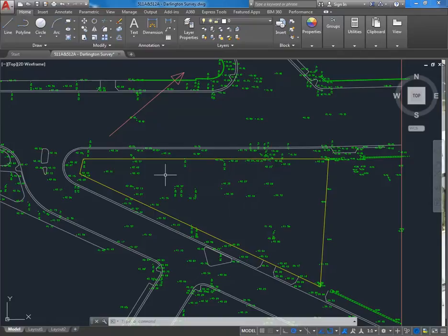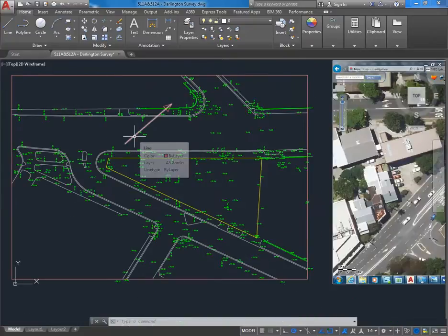And so these are the things you should be thinking about when you first set up your project. How are your plans going to be oriented, and how do you maybe need to then organise your other drawings to work with that? Don't always think you need to orient them to true north. That's a common mistake. People think that because engineers and other people often orient their drawings that way, that you need to have architectural drawings with north at 90 degrees, but you do not need that, and it actually will create problems if you do it all the time. So you have, it's called your own project north setting, and that's an option you'll have in Revit as well.